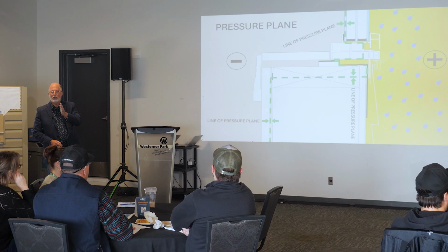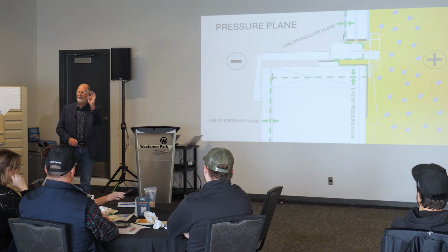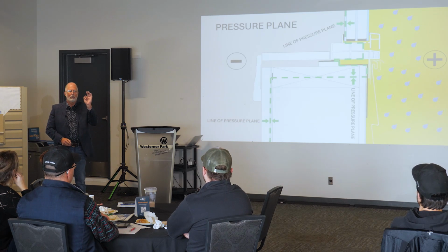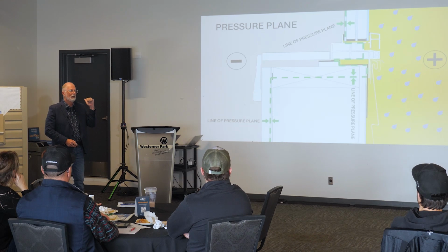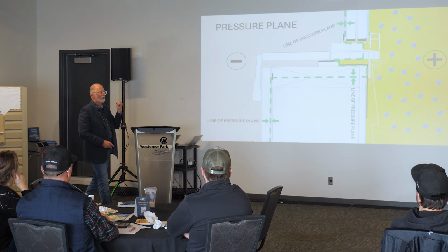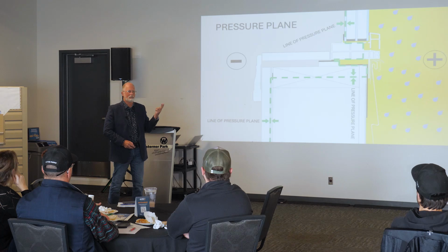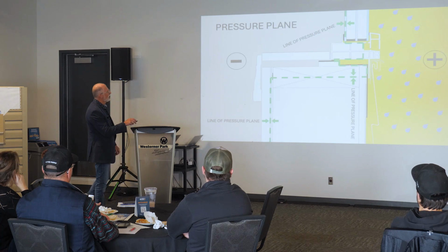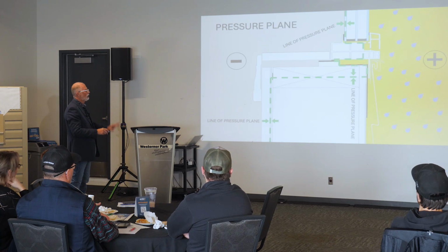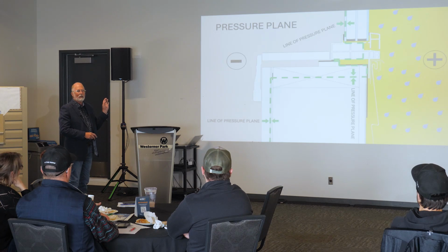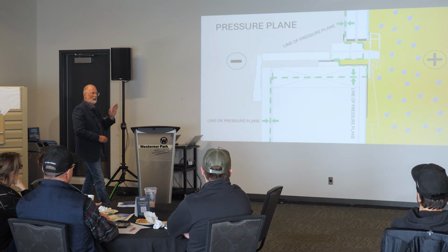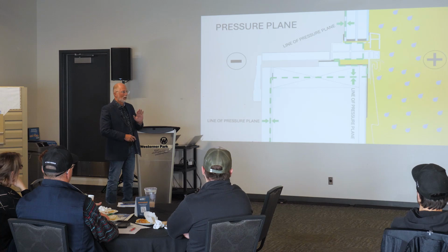And if we have water in contact with a hole and we have a suction, what does it take for water to go through an opening? I always use the mop principle, right? Moisture, opening, and a pressure. So if we can eliminate the opening, great. Or good luck, right? But if we can stop the air pressure, great or good luck.